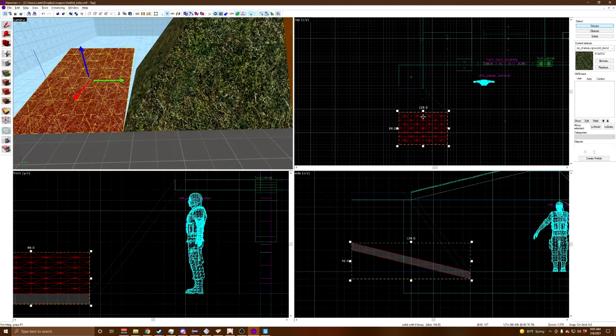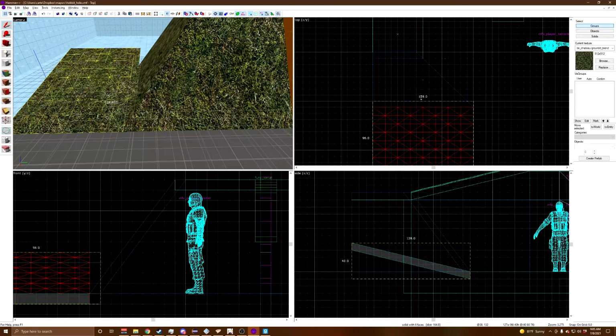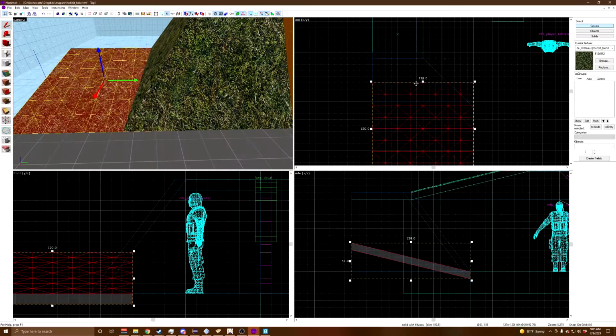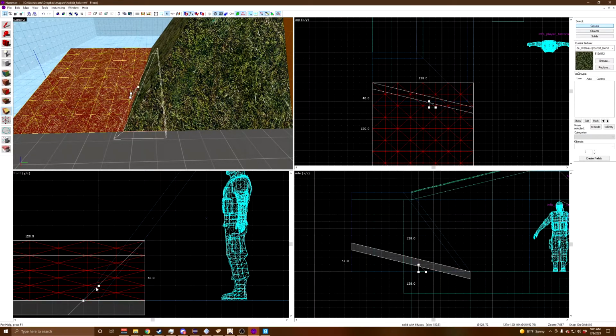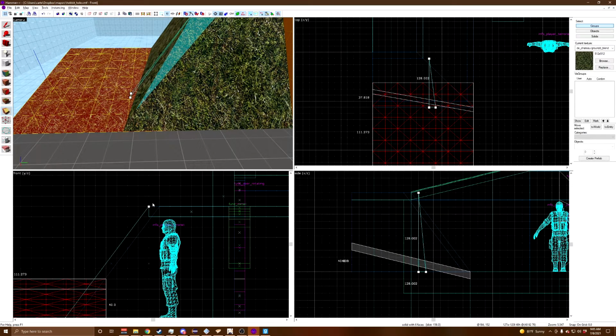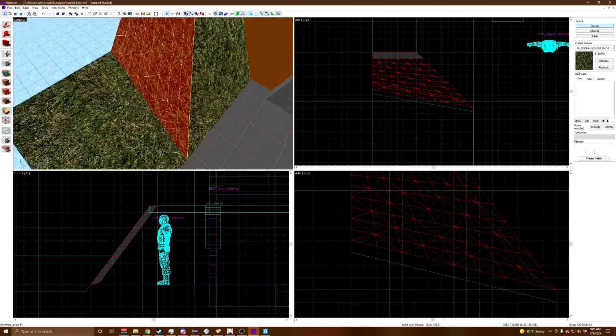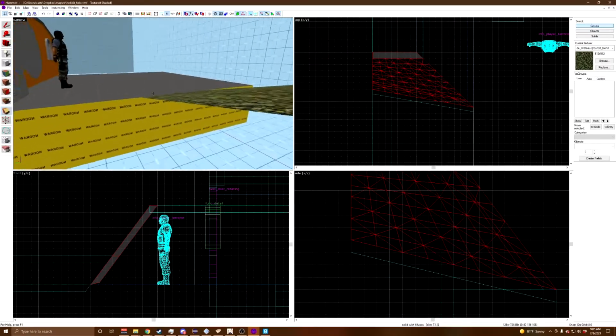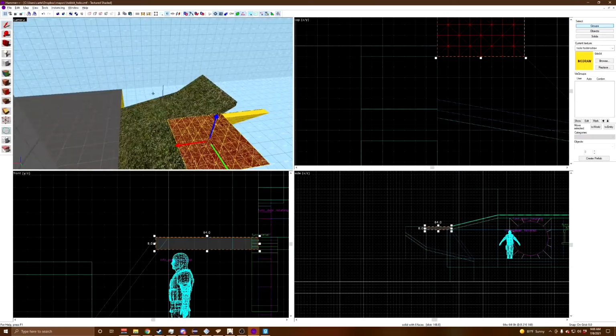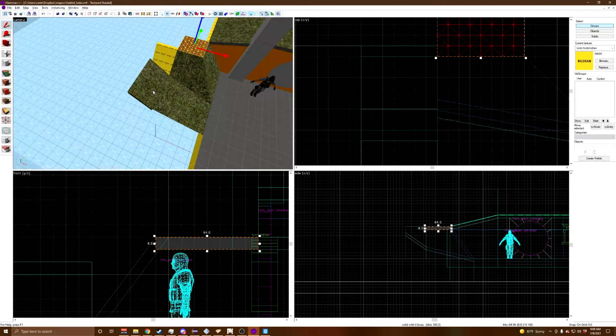Instead, now we need our ramp to meet in the middle with its adjacent displacement. So let's drag out our ramp so that it intersects with its adjacent displacement, and once again, let's use our clipping tool, but on the ramp this time, follow from one side of the slope to the other, and delete the unnecessary bit. These two displacements are now officially sewable. I'm now effectively going to repeat this process until I reach the top of the hill.